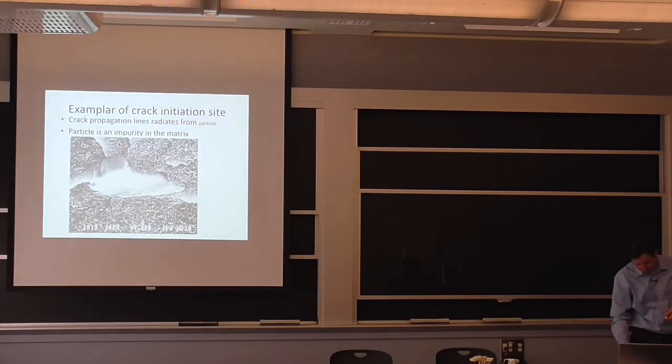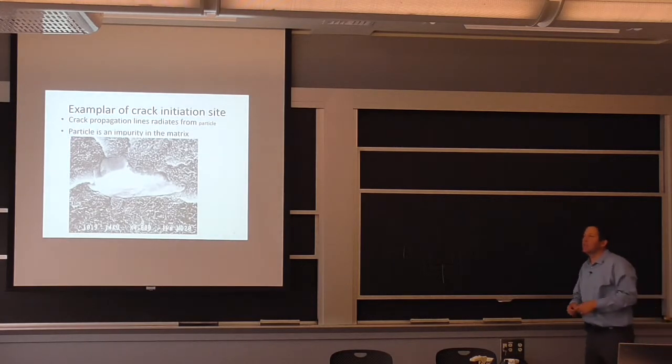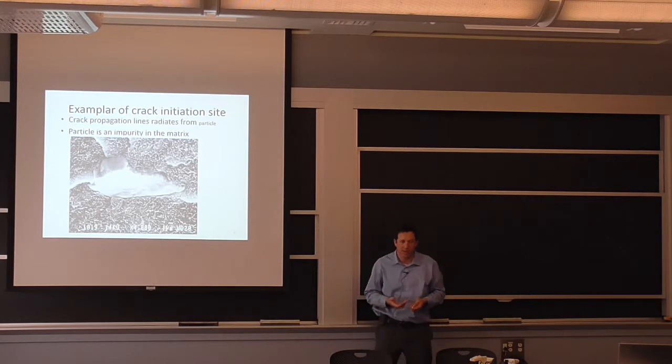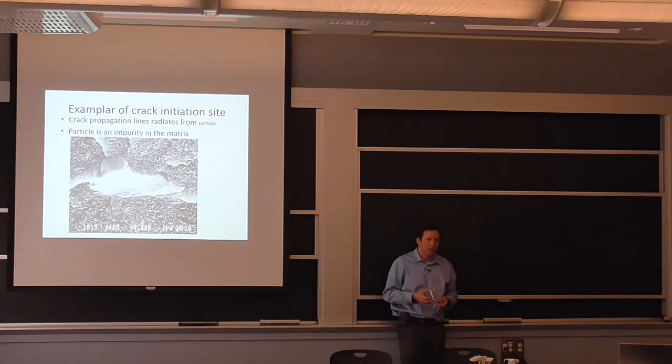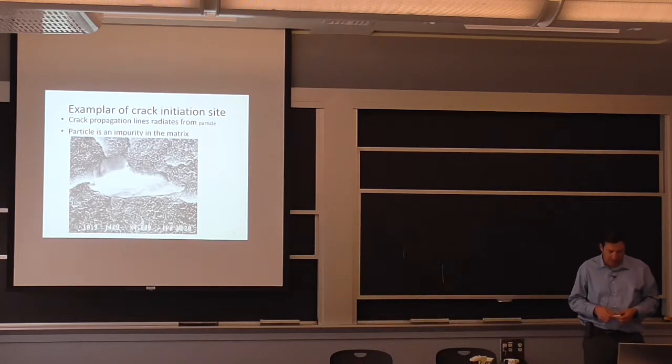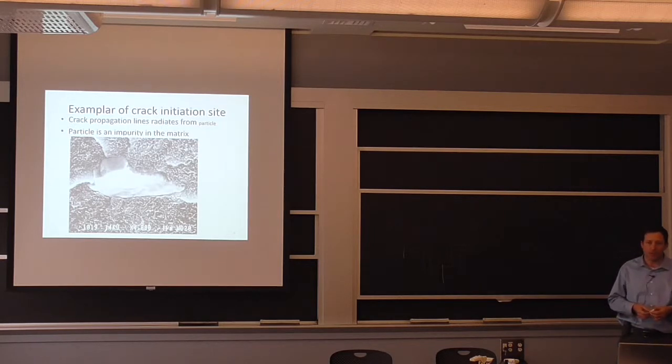Now, it's not to say that molecular weight or the length of the chain is the only thing that matters for this long-term strain. If you have inclusions, if you have notches on the surface of the plastic or vented parts, that would be where the cracks start.